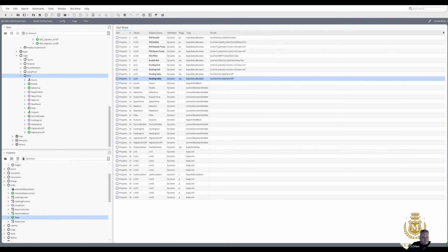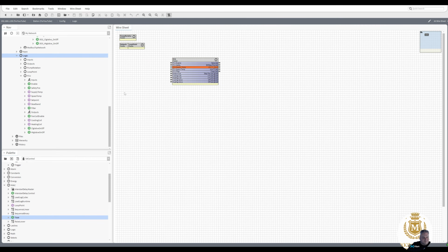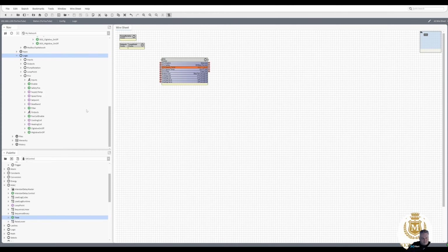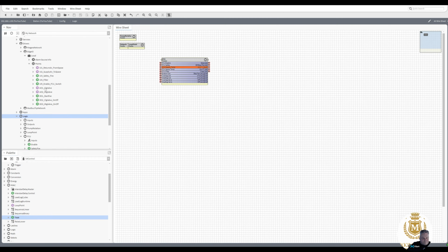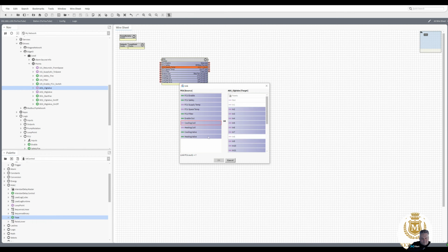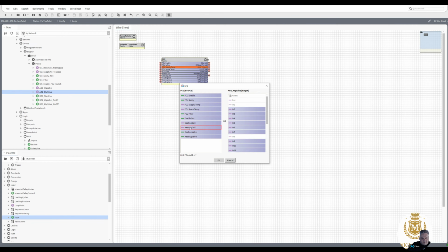So now when we look at the wire sheet, we've got these, so these need to go to the point. So I'm going to link mark that, and these are my points up here. So link from analog output 1 cooling coil, link to in 10 on that one. Link from my heating coil into in 10 on that one.